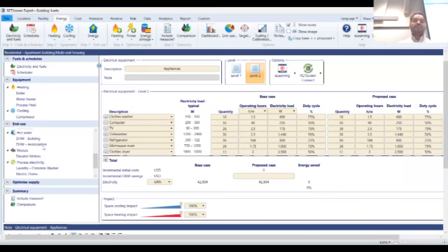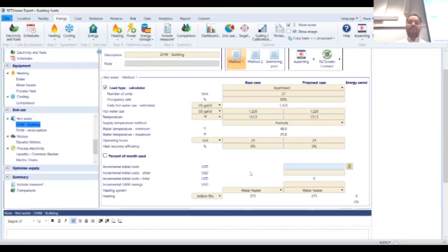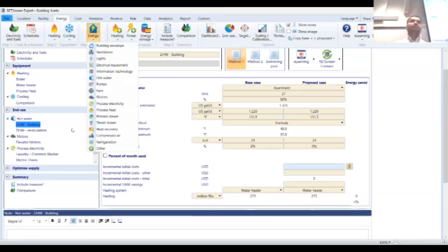Next step in the process, they have a domestic hot water system that comes in the bathroom. That is what we have defined out here. Since it is a residential building, we have selected the load type as apartment. We know the number of residential apartments and the occupancy rate, and accordingly, RETScreen helps to determine an estimated hot water usage for that particular project. If you have your actual usage from the energy audit, you can define that. You have the hot water supply temperature and the operating hours, and accordingly, it will estimate the heating usage through the domestic hot water.